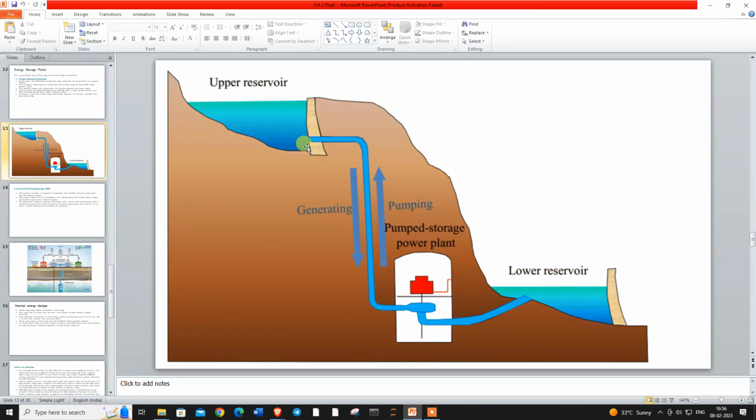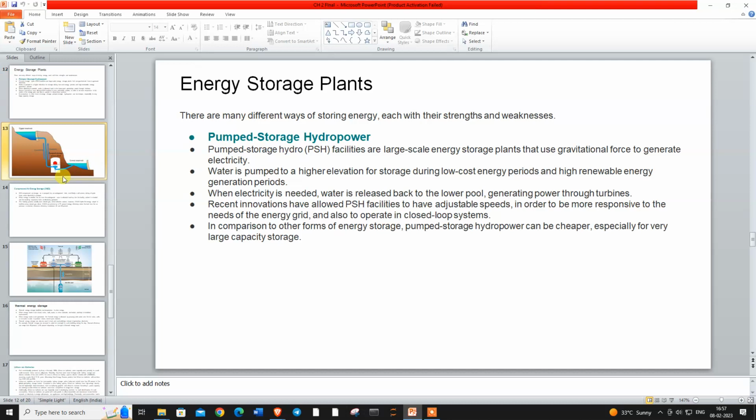So the amount of water is very small as compared to the general power plant. As compared to the Koyna and Radhanagari power plant reservoirs, this reservoir has very little capacity, so that the water can be pumped easily from a lower to a higher level. So this can be used for generating electricity as well as pumping water from lower to higher. As the cycle repeats, we can use this pumped storage hydropower plant for supplying the peak period, or the spike in a peak period.